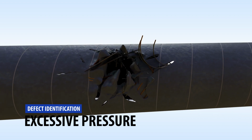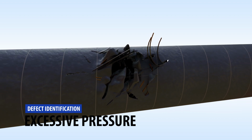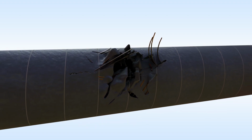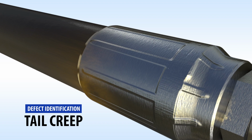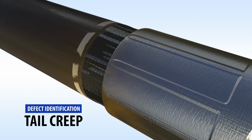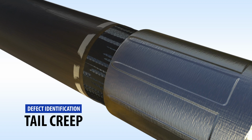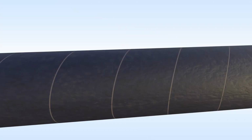In this instance, the hose, which was rated at 700 bar, burst at 1,586 bar. Tail creep. Leakage occurs between the ferrule and the hose. Important note: ultimately, the hose assembly may completely separate from the hose. A probable cause? The shell of the fitting was crimped too much or too little during assembly. Another potential cause of tail creep may be the result of mismatched components.